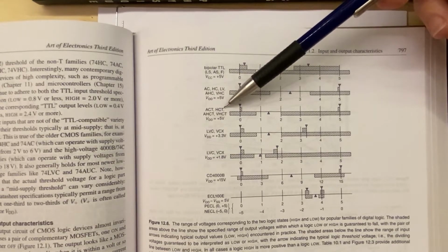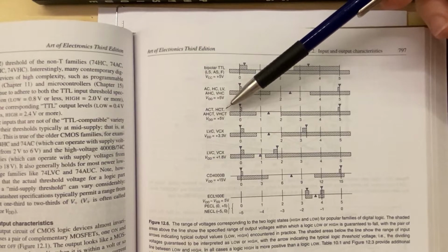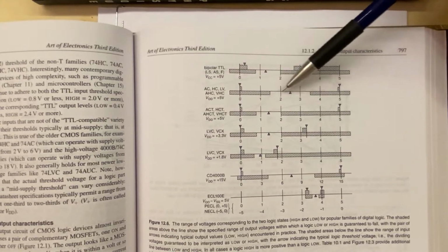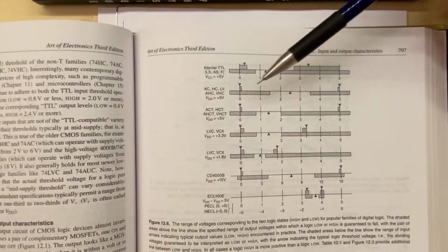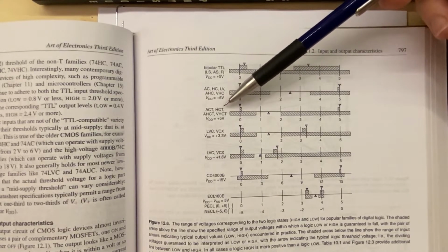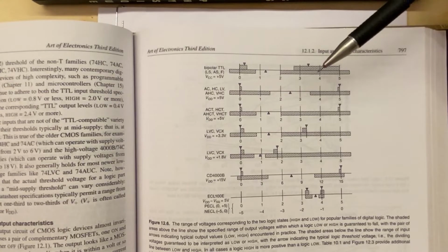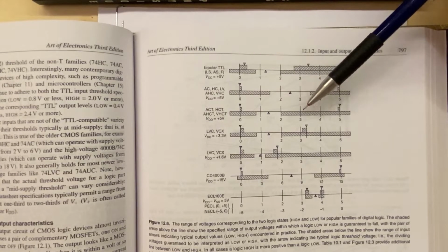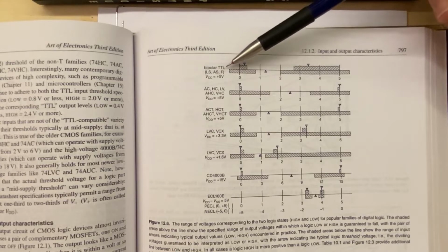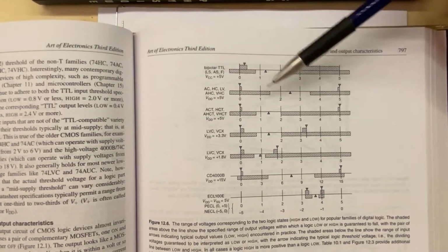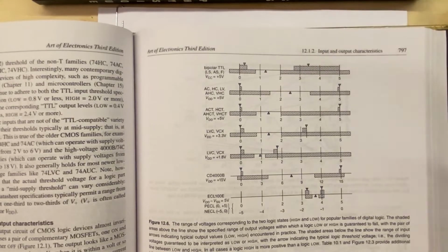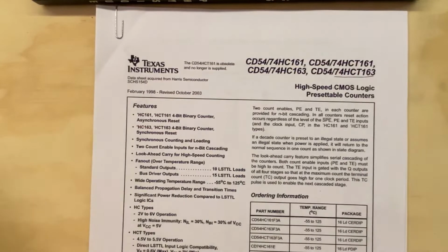Now the HCT is the one I'm using. Well, it's just the chips I have, so that's why I'm using it. It's for no other reason than that. I mean, the HC is probably a better choice because of this even division. But you get all the benefits of the CMOS chip, except they have this version just so that it could be compatible with the older TTL, since they were so popular before. And so it has the same logic division as the older TTLs. And that's the main difference between the 2 technologies.